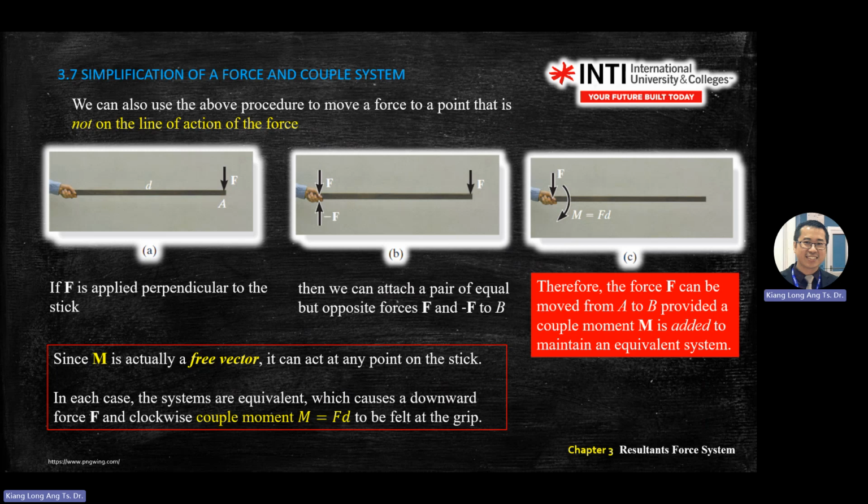You shift the forces perpendicular to the axis. You shift already with the distance. You transfer the force to one location plus the moment with the distance that you have moved. This one changes to this diagram. Okay, make sense? And the direction of the moment must follow the forces.